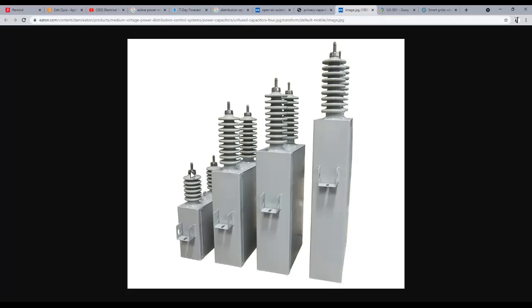Yeah, don't go too far with the battery business. It doesn't store for a long amount of time. But it can charge. So it doesn't discharge? Right. You're actually shorting the terminal so it's not able to charge. Surprisingly, under certain types of lighting, fluorescent lighting, these will charge. And when you have wind go across these things, they will charge the capacitor up to a lethal amount of voltage.